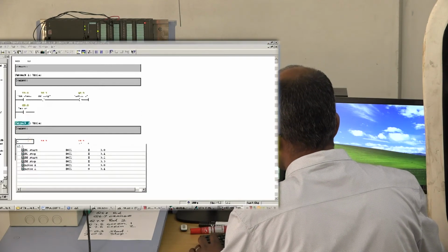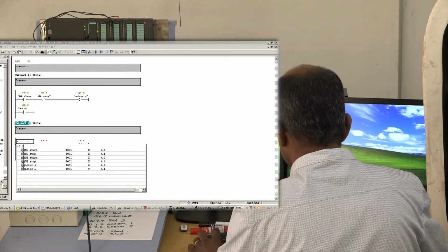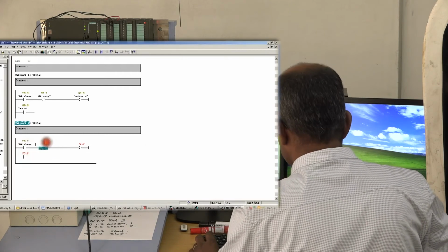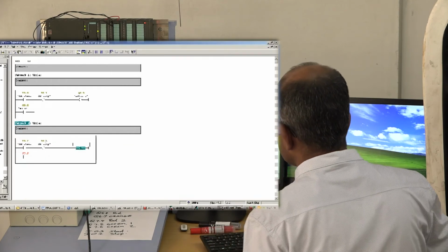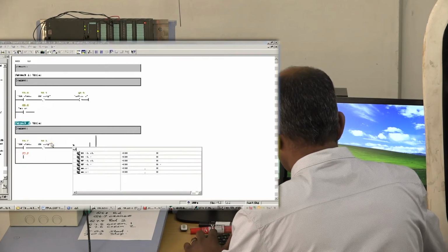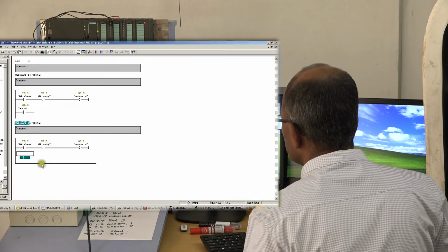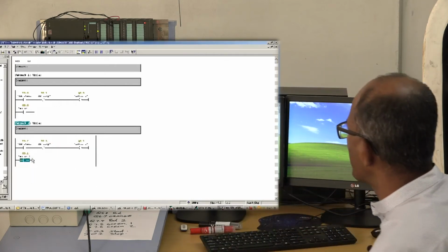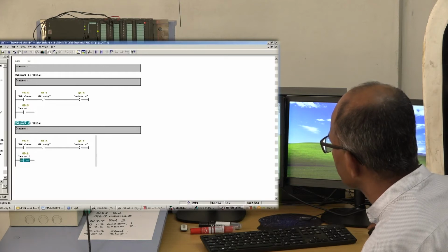I'll do the same for the second circuit, I0.2, actually I0.3, 0.2, M2 start, I0.3, M2 stop, Q0.1, motor 2, and this again, the auxiliary switch will be Q0.1, motor 2. I now have both my circuits. I want to save this.